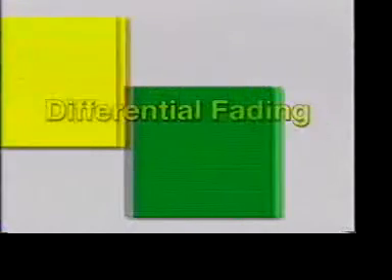Surrounding buildings, trees, and other sources of shade will reduce exposure to the sun's ultraviolet rays and thereby slow down UV degradation of the color. A particular symptom of this problem is differential fading. This occurs when one colorant in a formula fades faster than another, resulting in a shift in the hue from the original color, not just a lightening of the same hue. In this example, yellow and green colorants are blended to make a lime green color. With UV exposure and time, the yellow fades more than the green, so the color shifts in the bluer direction.